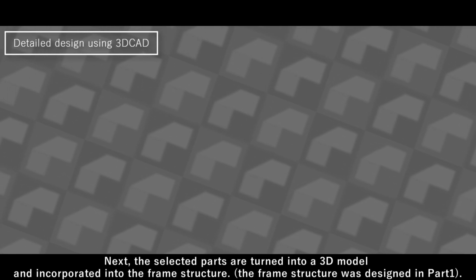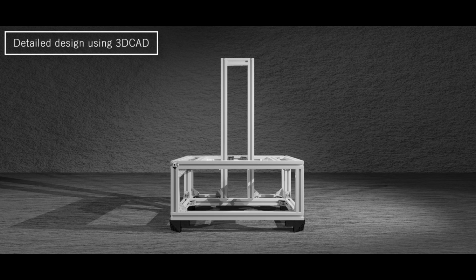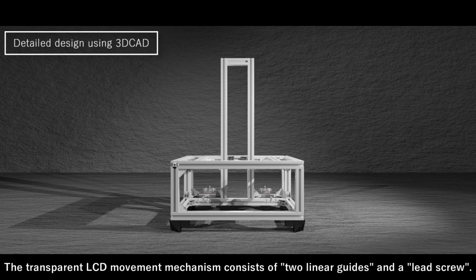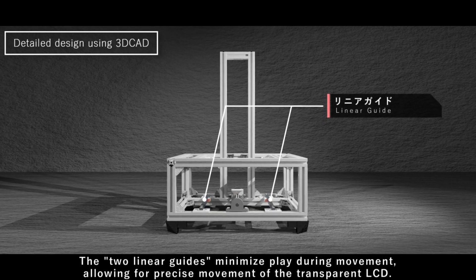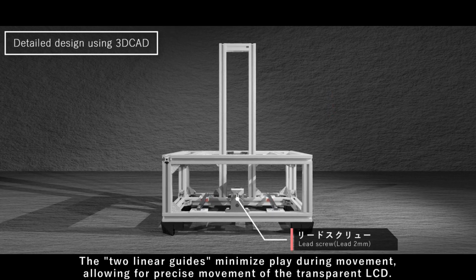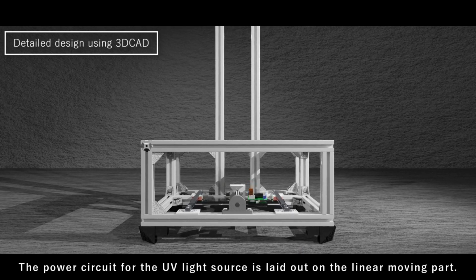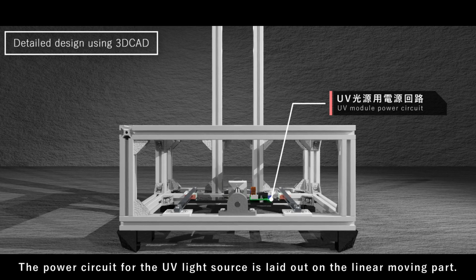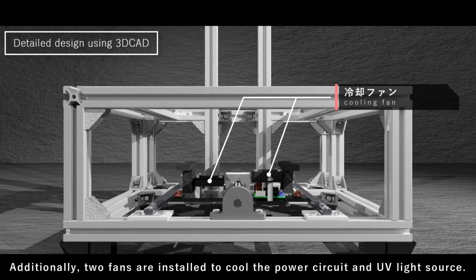Next, the selected parts are turned into a 3D model and incorporated into the frame structure. The transparent LCD movement mechanism consists of 2 linear guides and the lead screw. The 2 linear guides minimize play during movement, allowing for precise movement of the transparent LCD. The power circuit for the UV light source is laid out on the linear moving part. Additionally, 2 fans are installed to cool the power circuit and UV light source.